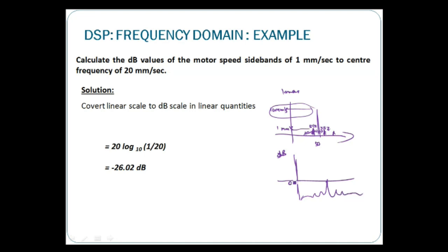Okay, so at that particular peak itself, the value is 0 dB, because 10 over 10, log 10 over 10 is log 1, which is 0. So whatever is below these zeros are negative values of dB, meaning these particular frequency components or this particular sideband is not dominant, or not higher than this particular frequency.